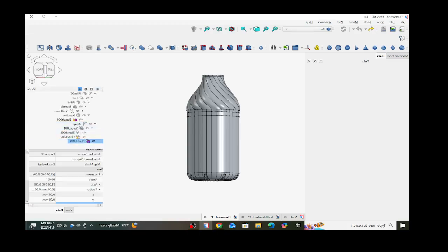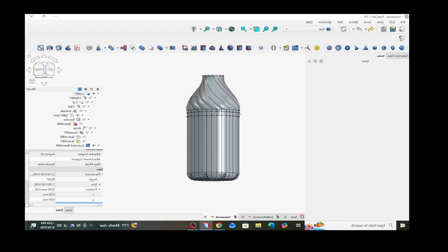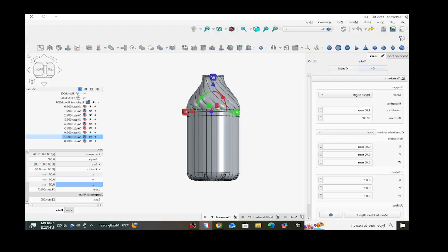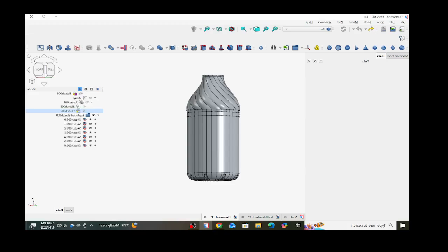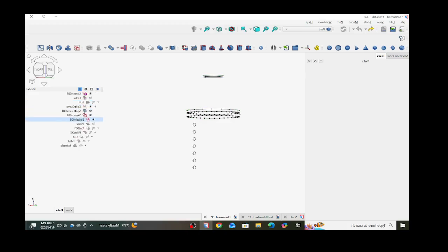Go into sketch 009, part, compound and explode compound. Now we have our exploded sketch with all these different circles. Now there's 9 components to it. See if I can turn off our, there we go. Hide our loft, sweep, and extrude for now.